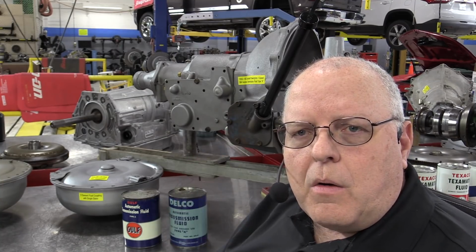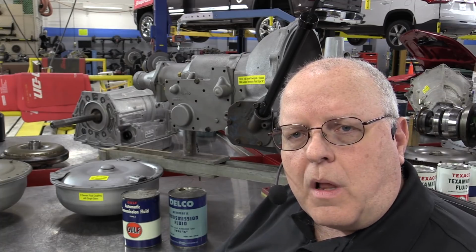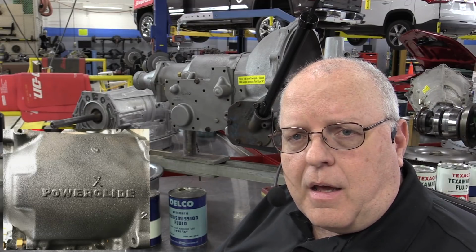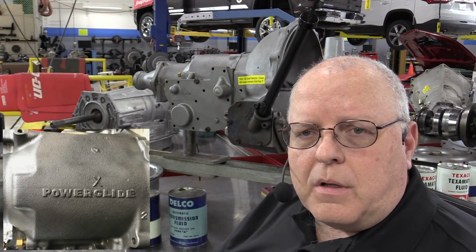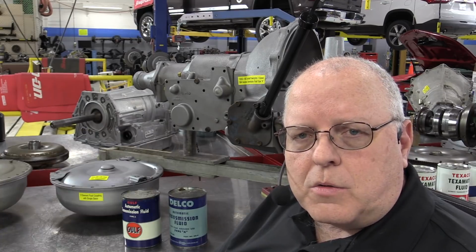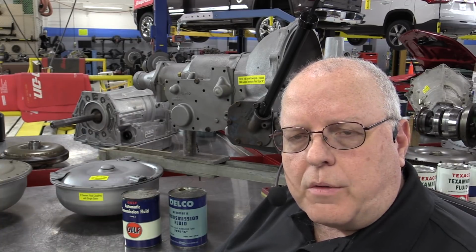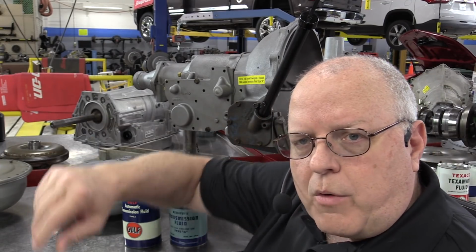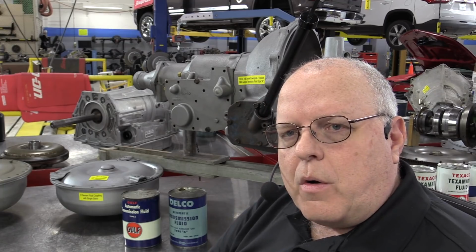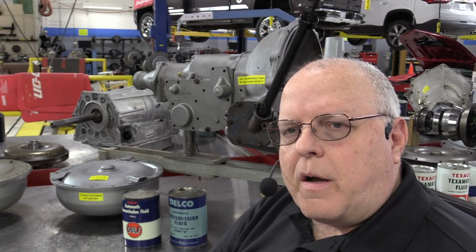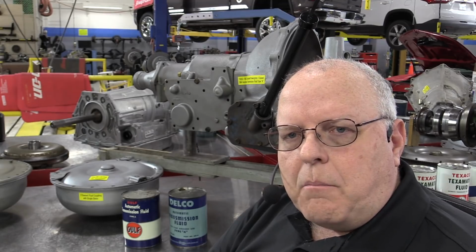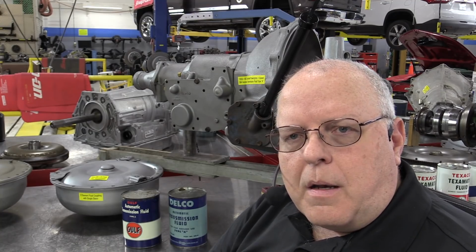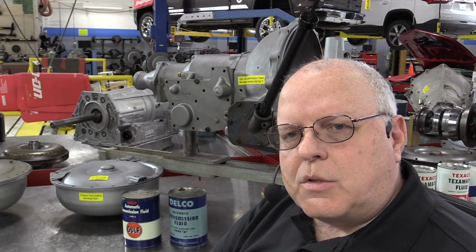Now, right behind me here, we have the cast iron Powerglide transmission from Chevrolet. This came out in 1950. I told you Chevrolet was looking for a less expensive transmission for their models of vehicles. Chevrolet also developed a special torque converter for their vehicles. It's this 3-element torque converter right here. That torque converter design is basically the design of torque converters today, minus the torque converter clutch. It's a 3-element design with a turbine, an impeller, and a stator, a single stator.